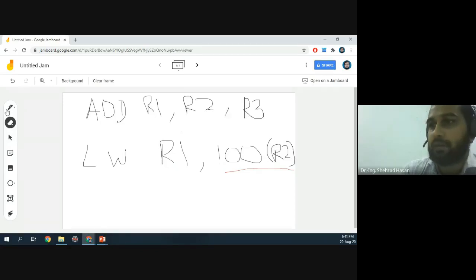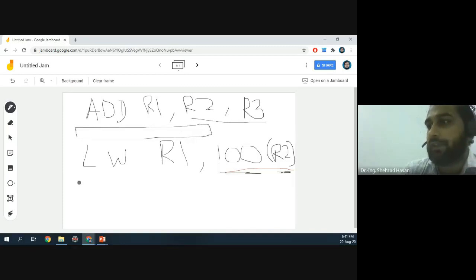So you can see here what I wanted to say was that sometimes you have got two source registers, sometimes you have got just one source register and some immediate values, right? But reading of register is going to happen in the decode stage. If you look at the instructions, these are the instructions that I've written in assembly form. But if you look at the instruction format that we discussed in the last class, their instruction formats are going to be a little different.